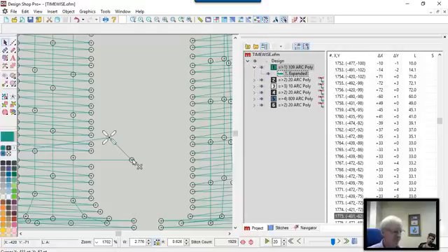One other caveat, you can expanded edit both expanded data as well as wireframe data. So if you are working in a wireframe design, you can use expanded editing to move those individual stitches. The difference is with those wireframe designs, if you go back in and you change one of those wireframe points, it will recalculate and regenerate all of those stitches, and so your expanded editing will be lost, but it will warn you before it does that. Exactly, and it will store it that way too. So everything is just right except for one or two stitches. You can edit it, still save it as OFM, and it will remember that you moved or modified a couple of stitches. So this is a slow way to go, but it can make a big difference.